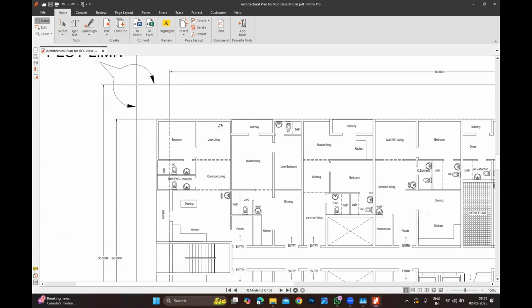If you don't reduce the slab thickness, automatically your foundation thickness will shoot higher. I'm not talking about the plan dimension of the foundation. I'm talking about the thickness of the foundation, because the thickness of the foundation is automatically governed by shear. Right. So these are the three points. What is the fourth point actually?